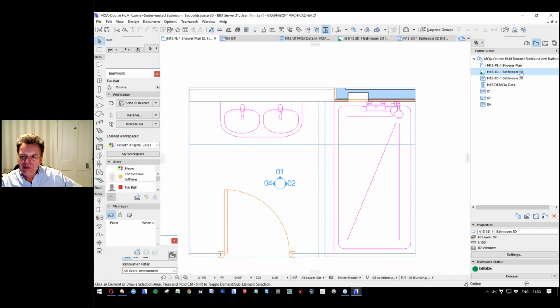So you've got... Why did you make the tile separate from the backing composite? I want to be able to measure the tile quantity and specify the tiles separately. I see, okay. And because it's a relatively small, fairly easy thing to do, I can do that. I do actually make some of the finishes on walls separate on some projects. We do that a lot where we're actually doing external insulation onto an existing building. You have to draw two walls, and you end up with lots of empty openings to put in as well. It's a bit of a pain, but there are techniques to speed it up.